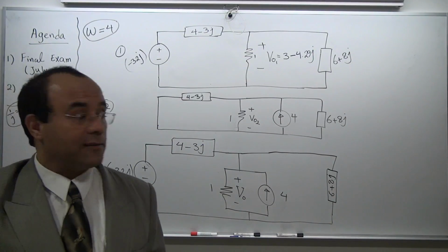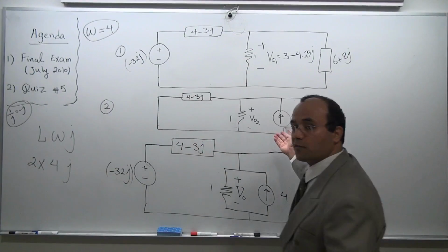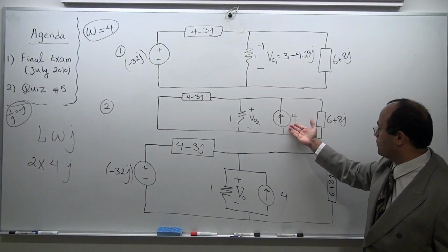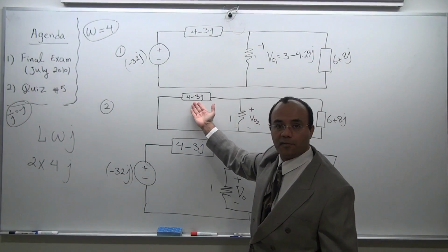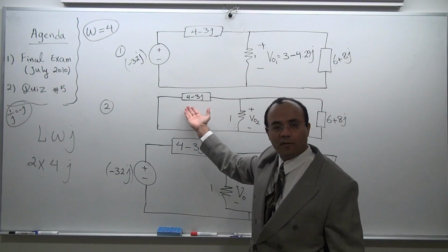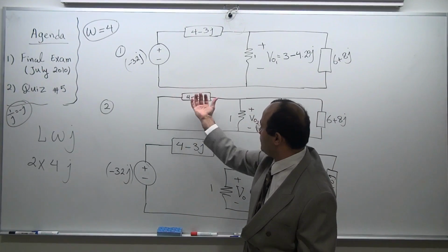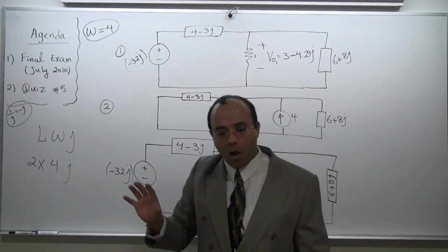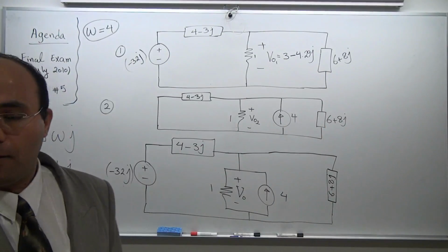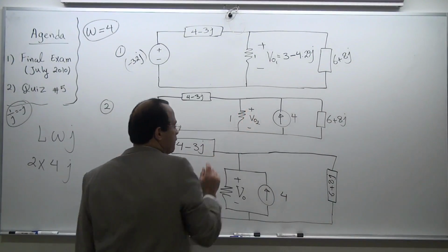Now let's take a look at the second design. The second design is no stranger to us. You have a current source. You have a resistor, and then a resistor. This is horizontal, but obviously this is a rubber band in your mind, right? You can grab this and actually you can see that this component is in parallel with everything else. All four components you see in the middle are actually in parallel. And the voltage I need is the voltage of 1 ohm.